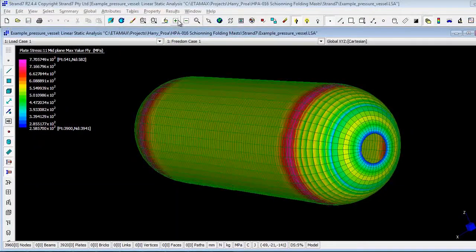In a matter of minutes, we've managed to create an FE analysis for the complete pressure vessel with 3 layers in this case, but as many layers as you'd like, with as many different winding angles as you like. It was quite easy thanks to the CADWIND export to FEA option.